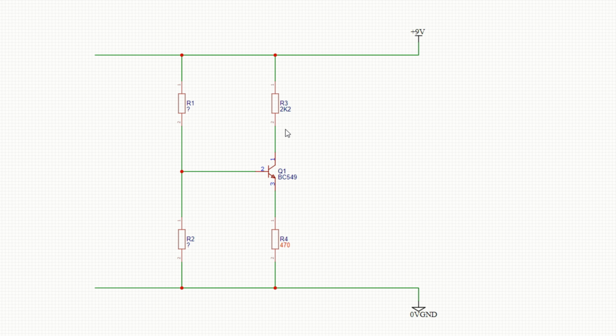So to give the maximum signal range, the collector voltage wants to be somewhere between half and 2/3 the supply voltage, because obviously when the transistor turns fully on, you've got 5 and 1 units value, so you've got 6 units of resistance, if you like. So you've got 1/6 of the total supply voltage, say 1.5 volts, on that resistor when it's turned fully on. So the range isn't fully from 0 volts to 9 volts. It's from 1.5 volts to 9 volts.